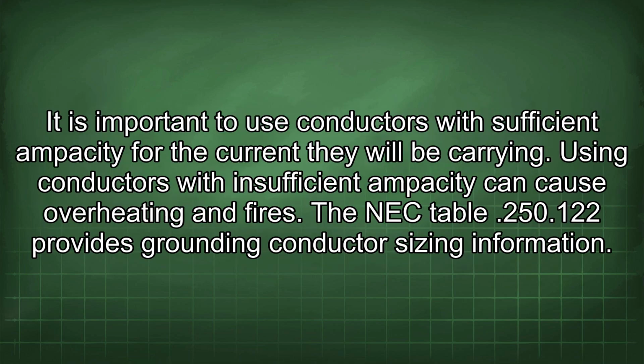It is important to use conductors with sufficient ampacity for the current they will be carrying. Using conductors with insufficient ampacity can cause overheating and fires. The NEC table 250.122 provides grounding conductor sizing information.